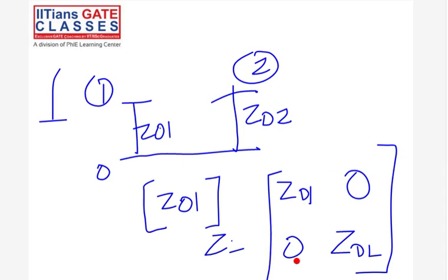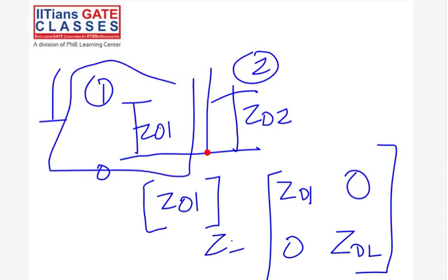Same way, if a current is injected at node 1, the voltage at node 2 is not affected. And the Thevenin's equivalent, if you look at from node 2, will be only node 2, not node 1. So basically, this is actually an example of an islanded system. This is an island, this is an island, right? Is that clear?